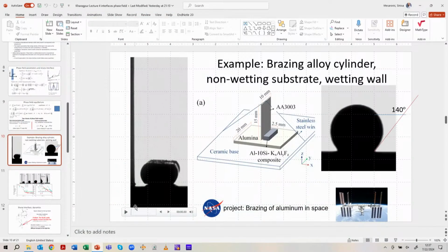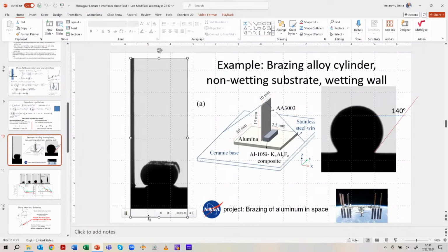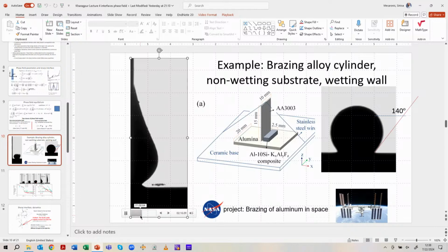Because if you look here, what happens is while this is melting, now this is collecting material, and it's turning into a sphere, right? Let's move a little bit forward. Now, when will it touch? Well, if it touches too early, then your material is full of solid residue, and it's very viscous.